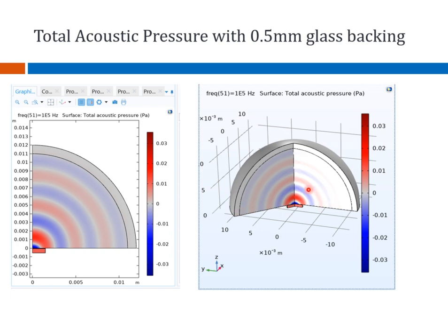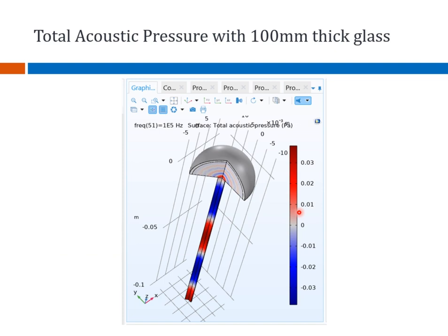This is a 3D view of what is going on. The CMUT is vibrating, and the membrane is generating waves into the air medium, which are absorbed by the matching layer. But on the rear side, you have a finite acoustic pressure that is representative of the sound wave in the backing, but the wavelength is very large compared to the thickness of the substrate. This is just for illustrative purposes.